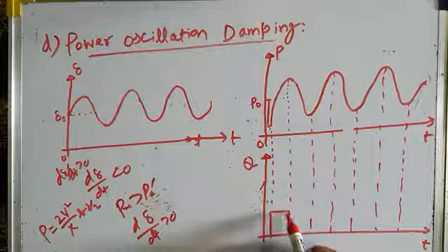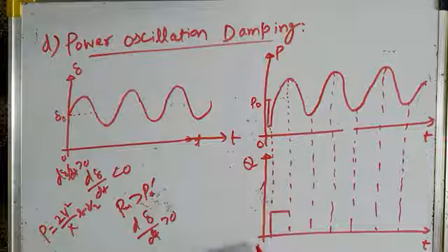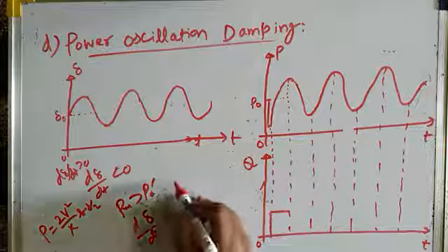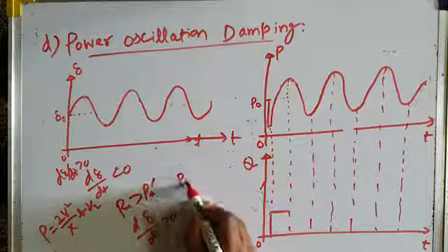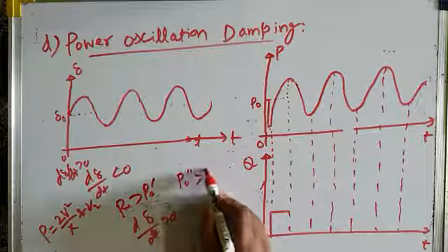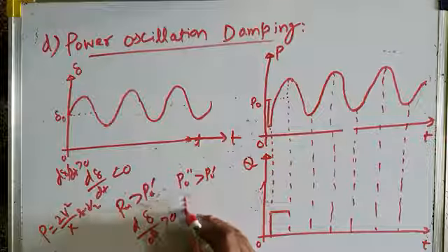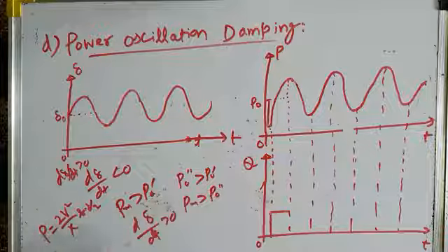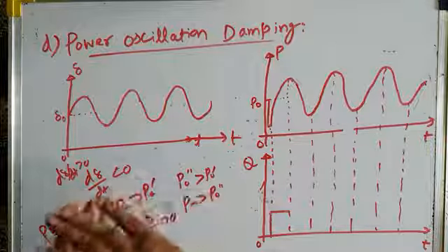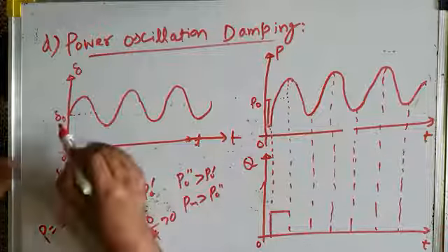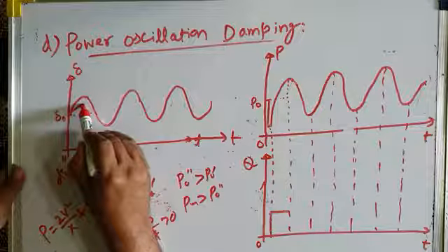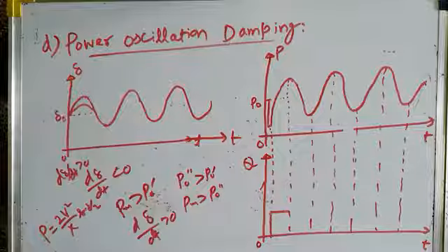So as soon as the shunt compensator injects the reactive power into the system, the line carries more electrical power. And when the line carries more electrical power, let's call that P0 double dash, which is greater than P0 dash. PM is still greater than P0 double dash, but this difference reduces. Because of that, the machine's acceleration reduces. And when the machine's acceleration reduces, delta will increase, but it will increase to a smaller value. Okay?